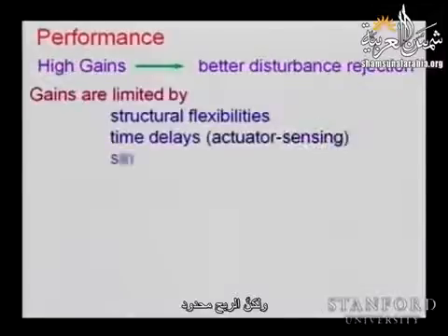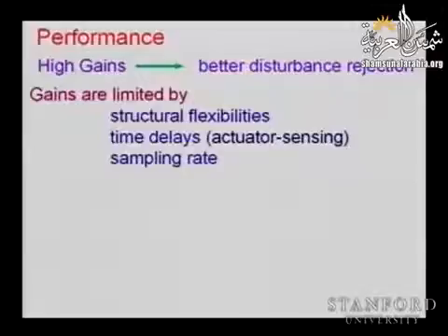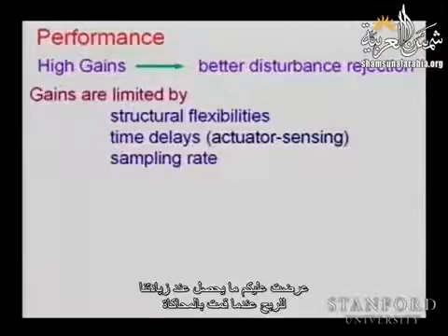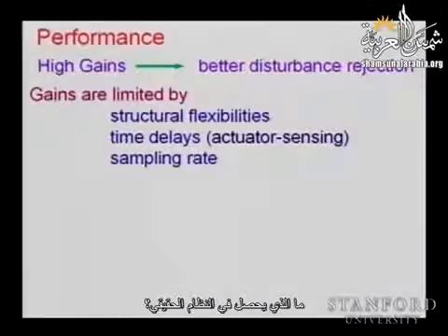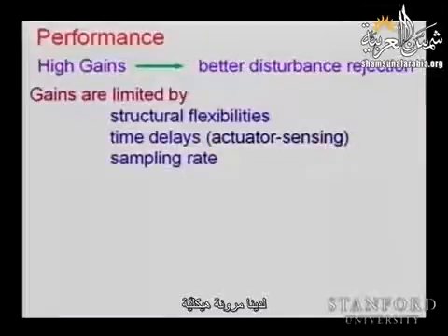However, your gains are limited. In practice, you start cranking up your gains. We had the simulation, and I showed you as we increase the gains, we reach a point when we start vibrating, and this was only a simulation. In the real system, what do we have? We have structural flexibilities.